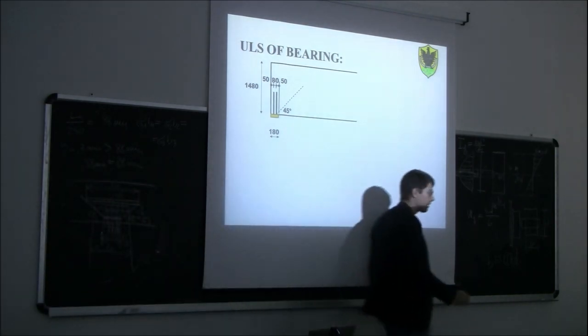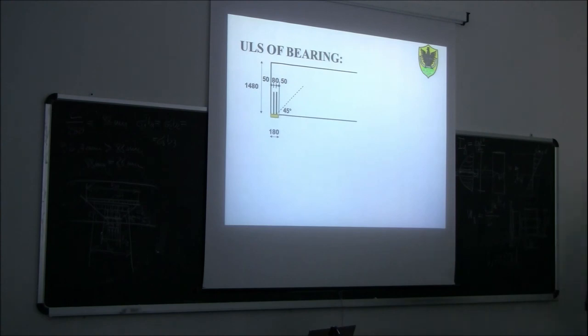So we consider the resultant constant at the different depths of the beam, but as we go inside here, we can consider a wider breadth over which to calculate the stress. And this breadth, this bearing length, depends on those two lines which are inclined by 45 degrees.